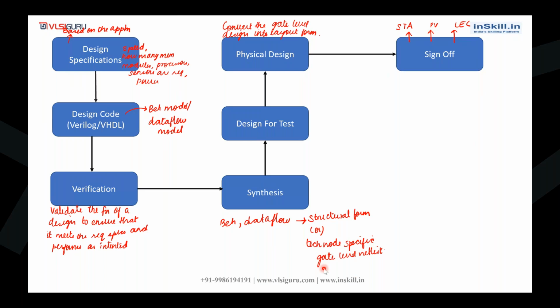And then we have the DFT team. We will be adding our own test structures into the design, like scan insertion, memory built-in self test insertion, boundary scan insertion, like that. And after this, we had the physical design team, where the gate level design was converted into layout form. So in each and every stage, our design is undergoing a lot of changes.